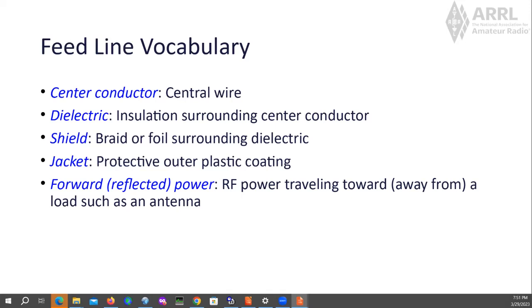And just a little more about the coaxial cables there. They're showing different types, and in general, the one on the bottom right is the best. And then probably that double shielded is, well, no, I guess the rigid hardline's best. And then the semi-rigid hardline, the semi-flexible, and then the double braided, and then the single shielded.